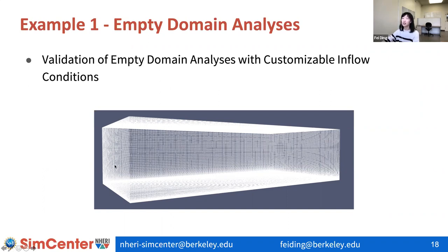at the inflow condition, you set up your target inflow profiles, but when the flow travels downstream, there will be some distortion of the statistical properties of your inflow turbulence velocities because of the assumptions of your turbulence modeling. You have relatively large energy dissipation or generation, or you have some mesh problems from truncation errors. So there are some issues with the distortion of inflow profiles, and you need to validate the inflow profiles downstream.